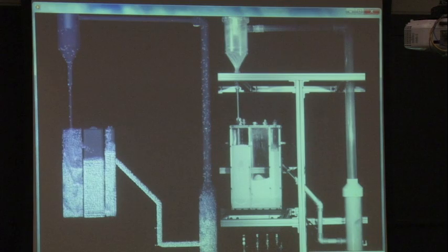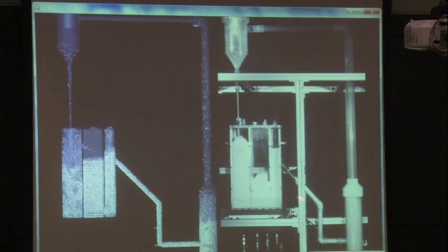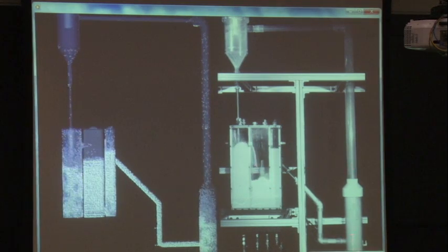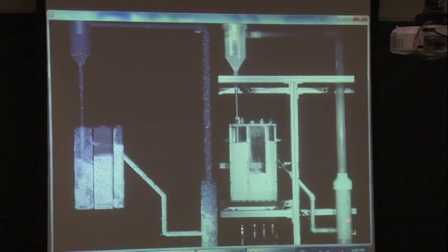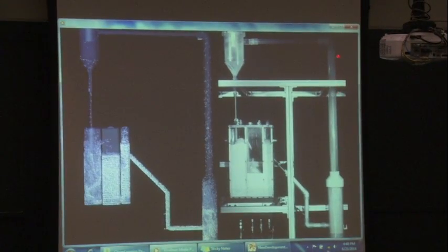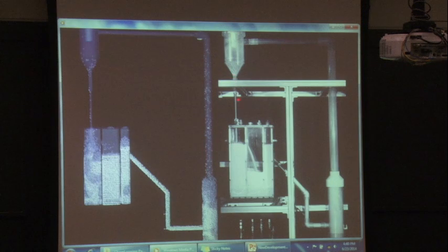The movie that you're looking at is actually a lab experiment from our lab where this is the air reactor. You can see the fluidization happening here, the particles getting carried up, knocked out in a cyclone, fed into this reactor, which is really a loop seal. That pipe extends down to the bottom here. The bed's being filled, and then we're fluidizing from the bottom.